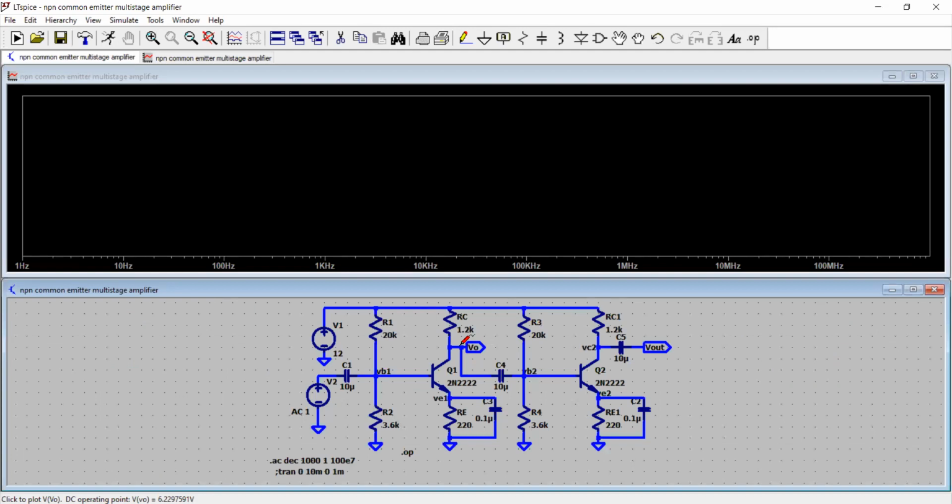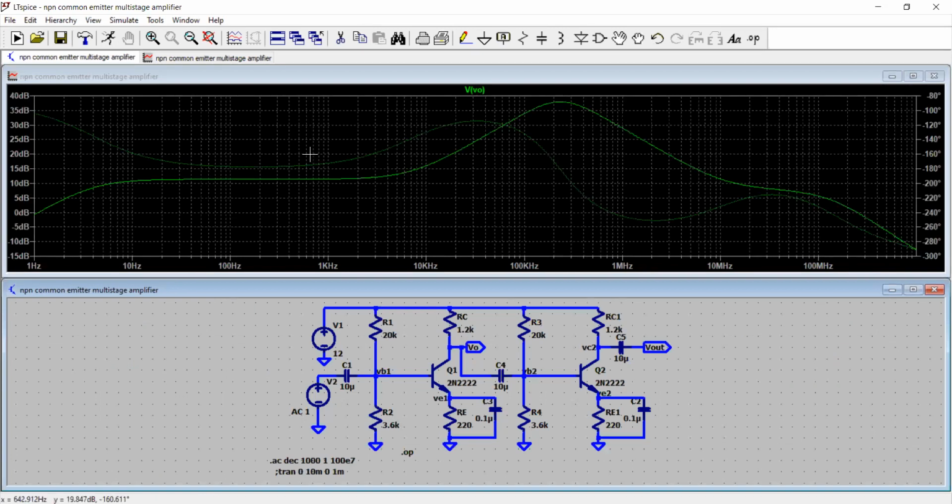Now look at the first stage amplifier output. The gain is constant here. Then you have like a band pass response in the middle. Our signal frequencies of interest are those for which you want the required gain. So for frequencies from approximately DC to about 1 kilohertz, you have a flat gain of 10 dB. Then you have a gain of 35 dB for the frequency about 100 to 200 kilohertz to 300 kilohertz.